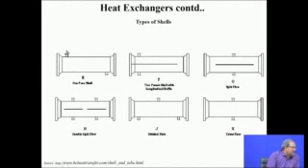So this is a one pass shell, the liquid is going to come in and it is going to move out of this. This is a two pass shell with longitudinal baffle. So the liquid is going to come shell side in this, it will travel, and then it will change its direction and will go out. In some cases, a split flow, this baffle what you see here, instead of being attached to one end, is right at the middle. So the flow pattern would be here, then it would travel in both directions and again come and meet the other part of the flow and go outside. So this is an example of a split flow.